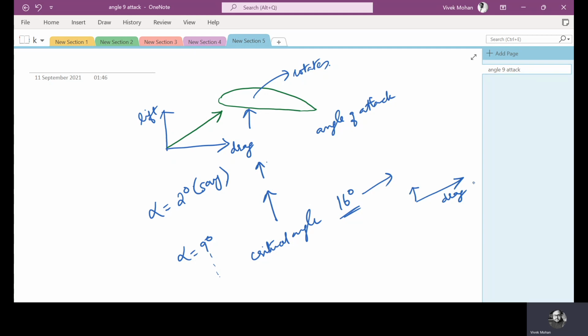This control is known as stall control, stall action, where after the critical angle of attack, the stall action gradually sets in, the drag force is greater than the lift force, and the blade rotation stops. When the drag is more, the blade decelerates and it will stop. So this is a braking action, or the control of power output could be done using this principle.